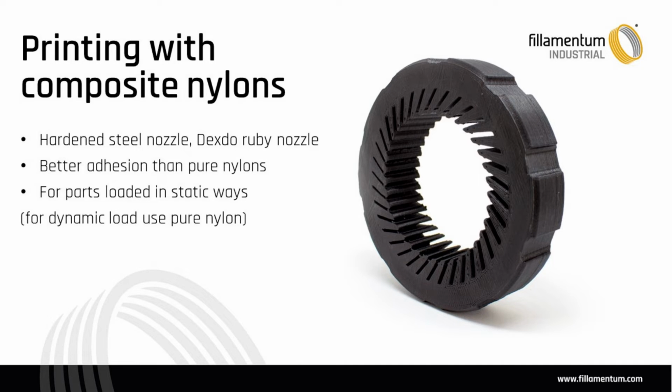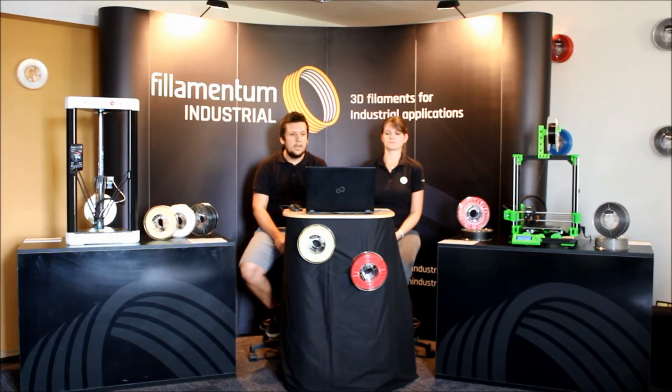If you are using hardened steel or stainless steel nozzles, please bear in mind that those two types of materials have different thermal conductivity, so usually you have to bump up the temperature a little bit, by 5 to 10 degrees, because of the thermal conductivity.